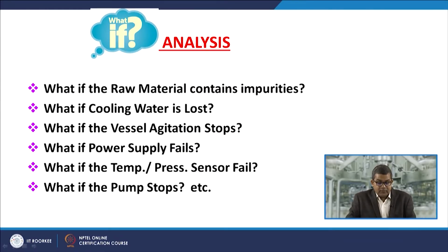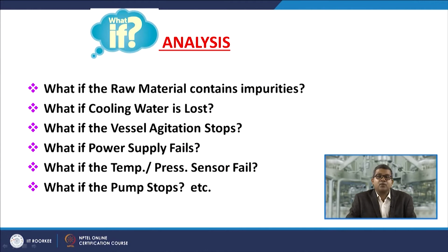What if the vessel agitation stops? What if the power supply fails? There are so many accidents attributed in the chemical industry that belong to the vessel agitation aspect or a power supply failure. What if the temperature or pressure sensor fails? Then sometimes you may not be able to record the things and the reaction will go away. What if the pump stops? So, etc. There are so many questions you can frame accordingly.